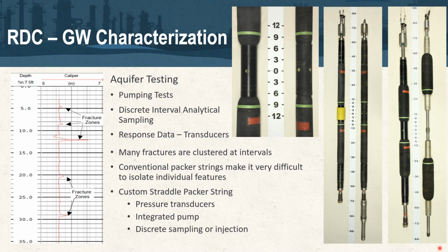Looking at the bullets here, this straddle packer has a Grundfos ready flow tube pump in the bell chamber at the bottom. It also has transducers located within the packer element itself: one above the packer for looking at hydraulic characteristics above the packer element, one within the element, and one below the element looking at vertical connectivity or vertical seal within the borehole itself.